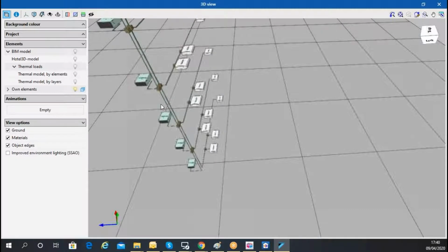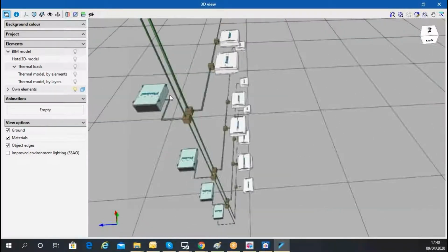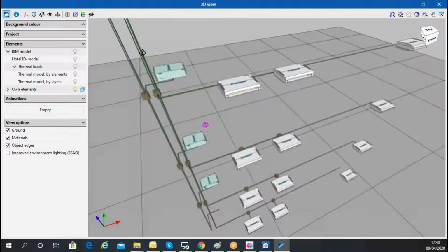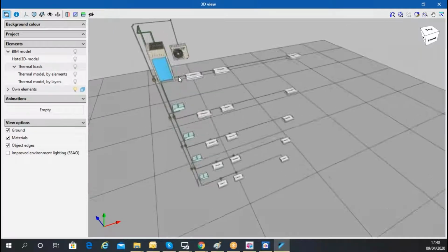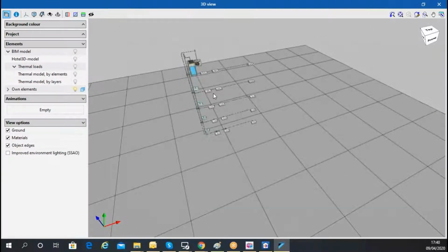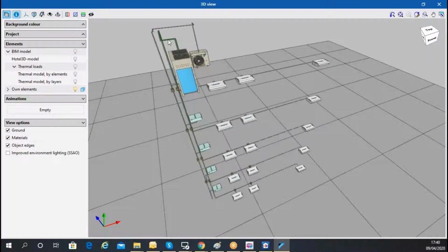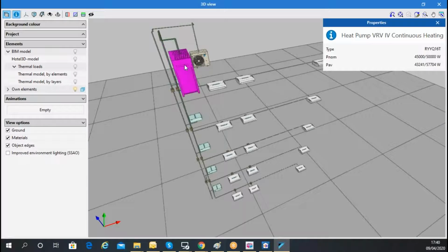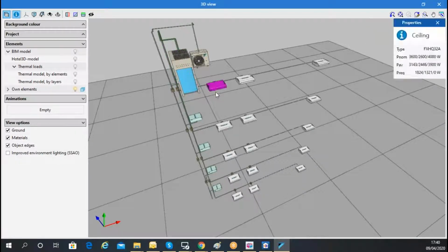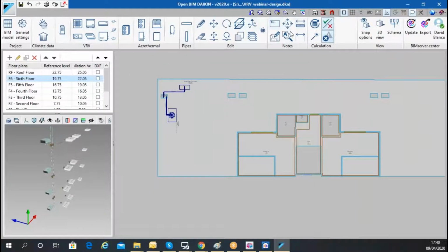We could see the information of the piping, the double gas liquid piping, and the connection with the two systems, outdoor units, with the different internal units for the ceiling and the ducting design. Here we could modify, consult the results, gas liquid piping, length and diameter, the outdoor units, and the internal units with the different requirements, and which checks the software is going to make.